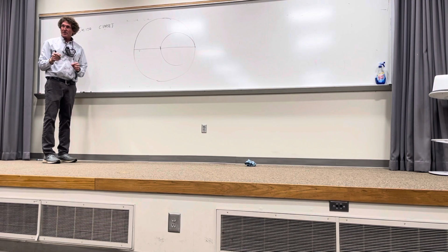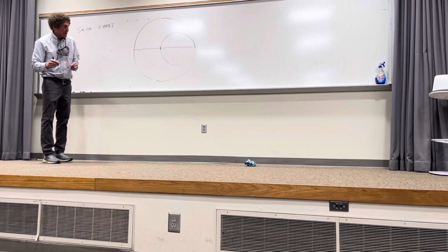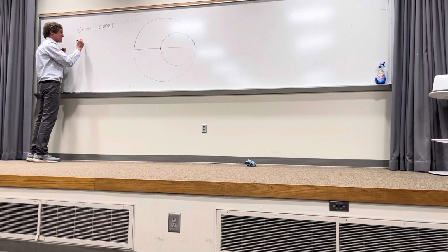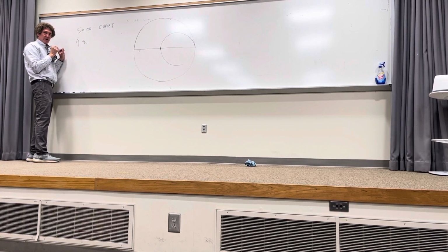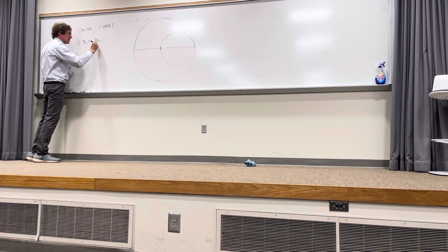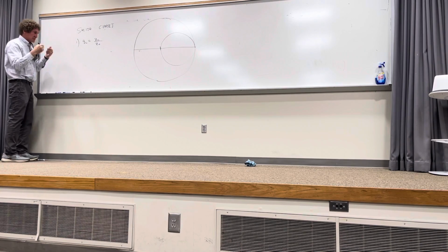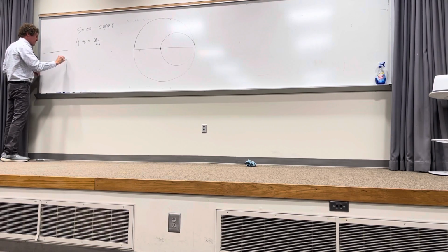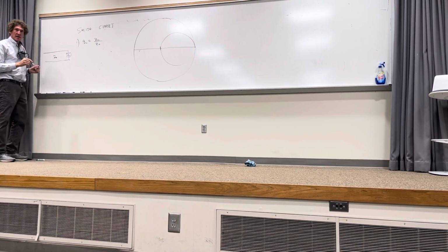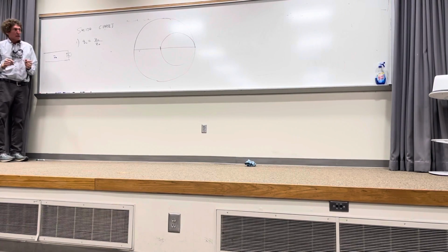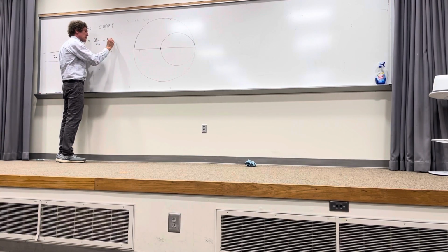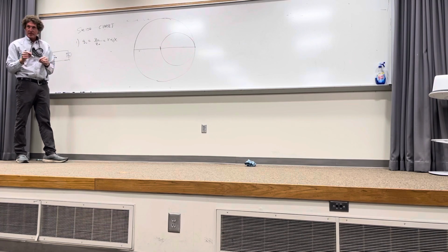Now, what I'm going to tell you is, with Smith charts, we take the load and create something called a normalized load impedance, ZL. And we take the actual load impedance, ZL, and divide it by the characteristic impedance of a transmission line. So everything I'm talking about is related to transmission line theory. Y'all with me? Now, this will have some real plus some imaginary component. Y'all with me? Everybody?